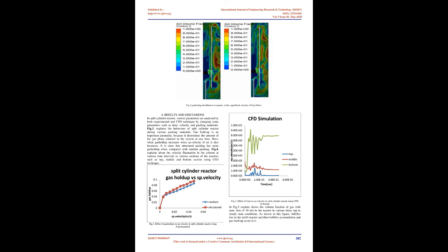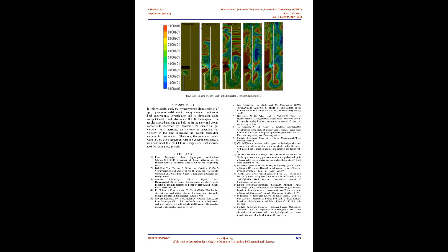In the current simulation, the Reynolds stress turbulence model and a 2D Eulerian model as the multiphase model were applied to study the hydrodynamic properties of gas and liquid phases in an internal airlift reactor under unsteady conditions. According to the simulation, the number of nodes was 45,000.